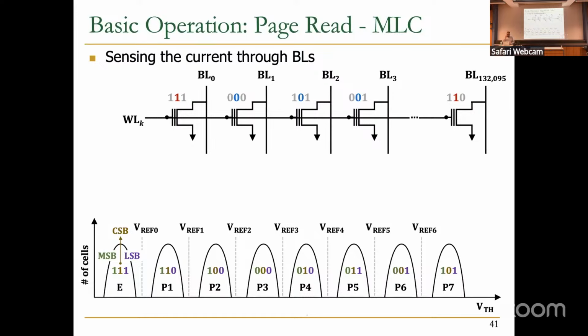So the procedure is that we first come up with reference voltages that are important for that CSP. For that, we check whether or not this CSP toggles. Here between this window and the neighboring window, CSP is still 1, right? So if I apply a reference 0, it's not going to help me at all for that CSP.